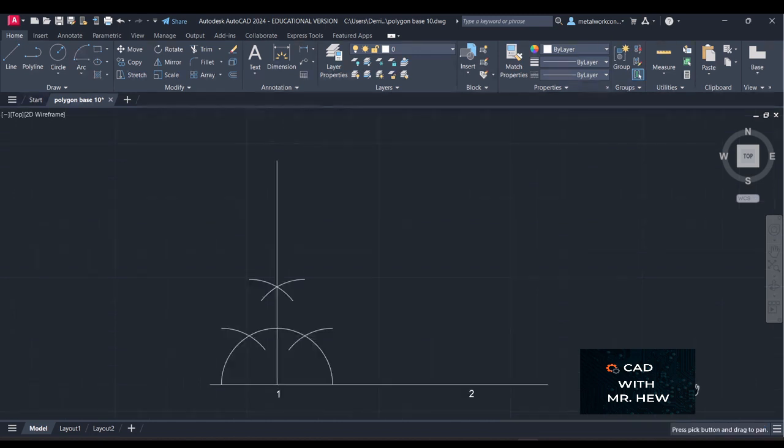What we have on the screen is a 90-degree angle constructed at 1. What you would do is draw arcs from center 1 to give you this semicircle here. Then with the same radius, we will put the compass where the semicircle intersects the baseline and mark an arc to give you this arc.